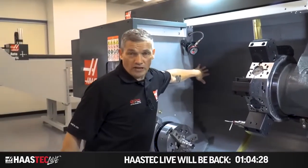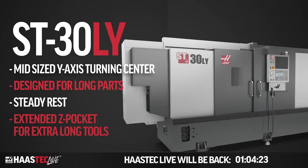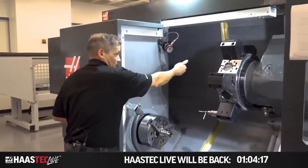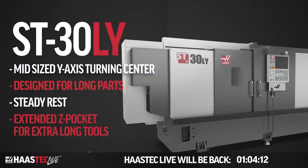Another cool feature about this machine is you can see this hole here, if you will. This is what we call the extended Z pocket, and this gives you a lot of clearance for boring bars and other really long tools, so that you can still get all the way up here to turn on the face of your part, and you're not gonna hit those tools against the bulkhead here. So ST30 long bed, great machine.